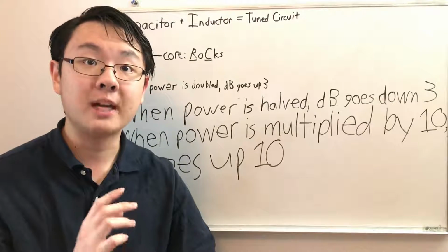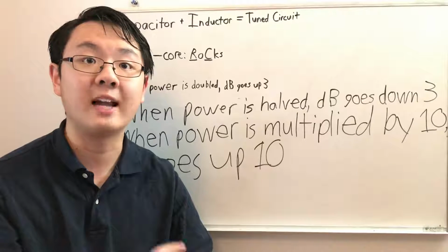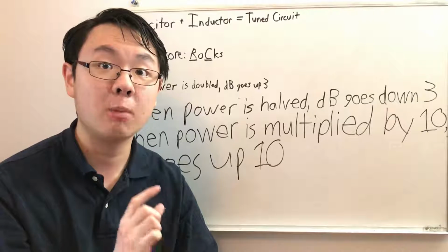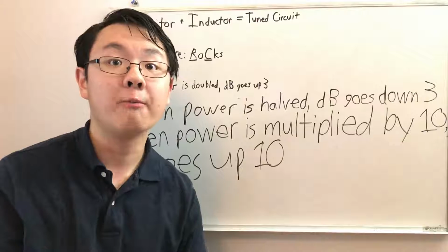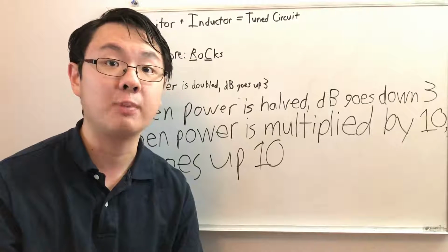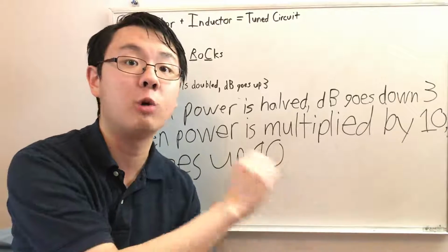One thing you need to be careful of when you're using multimeters is to make sure that your multimeter is set to the right setting. For example, if you're measuring voltage, make sure your multimeter is set to voltage, not to resistance. This is actually very important. In fact, I fried one of my multimeters because I set it on resistance, but then I plugged it into a cord into the wall.